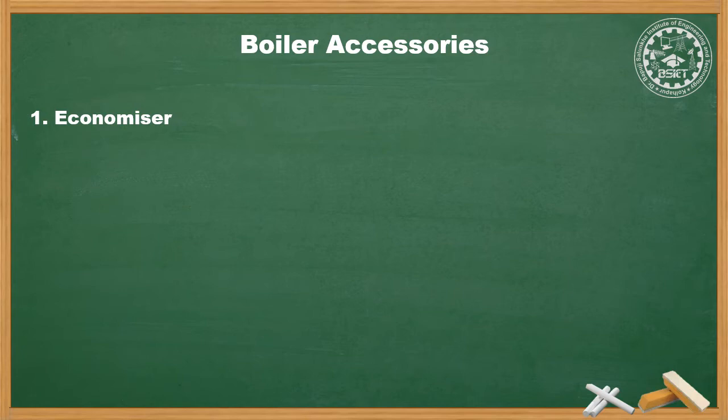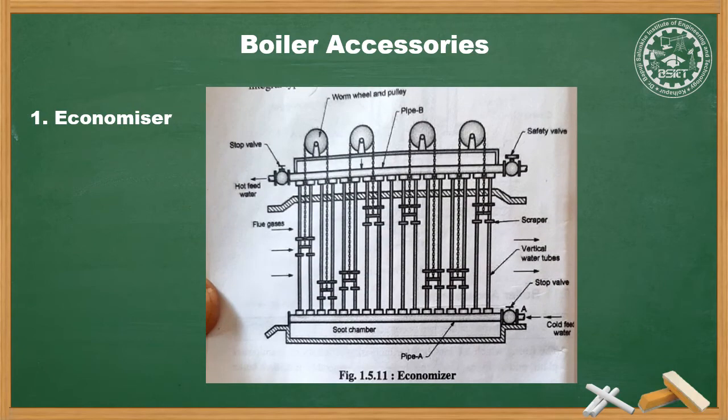In basic terms, an economizer is a heat exchanger. The orientation of the economizer can be horizontal, vertical or cylindrical, depending upon the size and space available at the boiler, and it is fitted directly to the boiler near the flue gases outlet. The below figure shows the economizer.